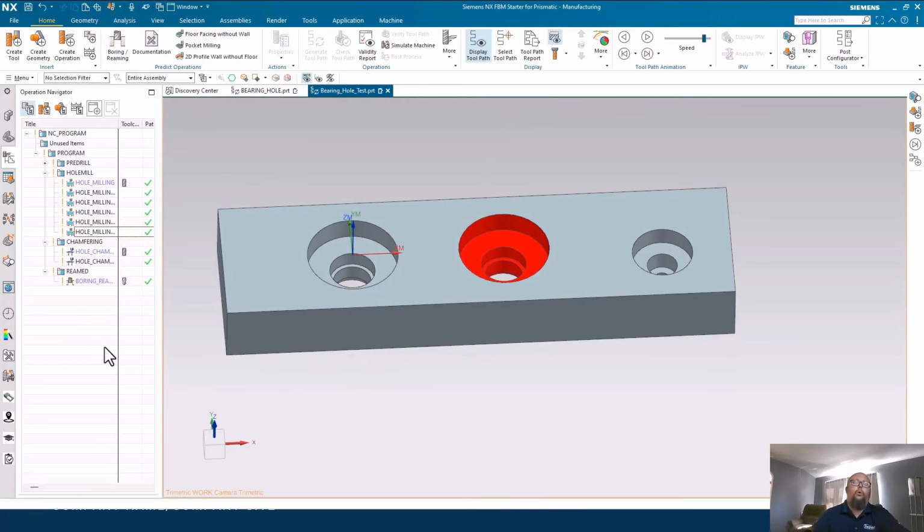It's also important to understand that if you have unique geometry to your organization, maybe some proprietary design, or maybe NX doesn't find the entirety of a feature as one object, maybe it finds a portion of some feature as one object and the other portion of a feature as another object, we have the ability to teach features inside of NX as well. So always something to keep in mind to reference as you go down the feature-based machining process.